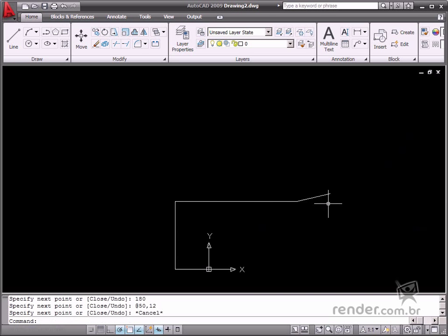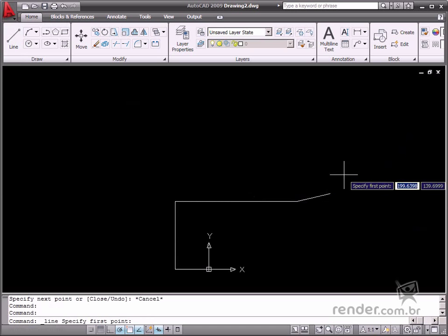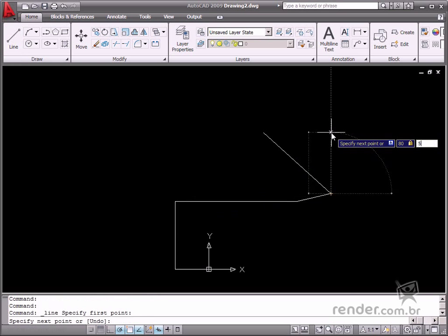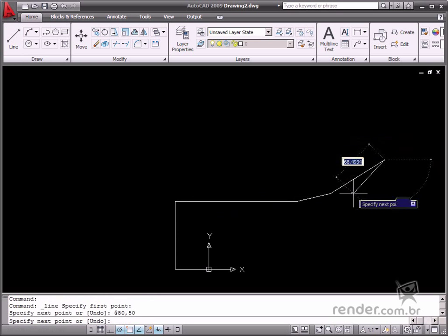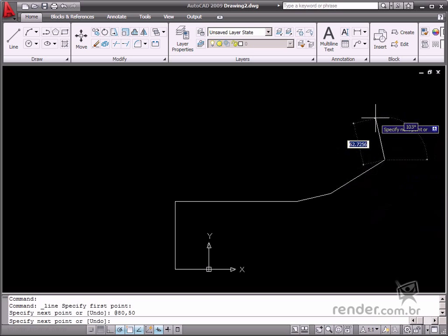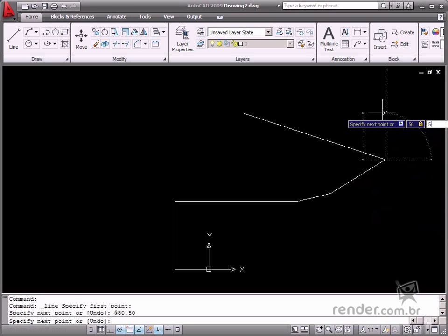So now let's learn about how to input coordinate values. There are 2 ways for defining coordinates: Cartesian and polar. You need to define values for the x and y axis for the starting and end points of the sketched entities in Cartesian coordinates. The xy coordinates are separated by a comma, so the program can understand the input data.